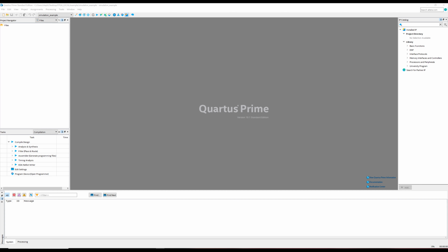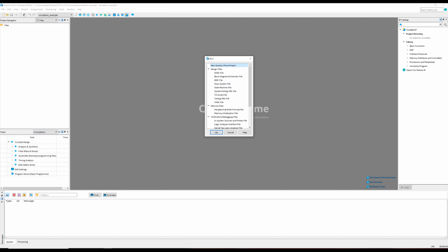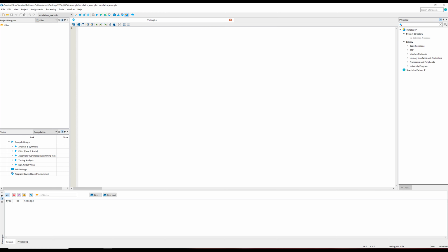Okay, in this video I will show how you can write a test bench and simulate any Verilog module or any Verilog design using that test bench using the Quartus design environment and Modelsim. So the first thing I need to do is go to File, New, Verilog HDL file, and I'll just paste my Verilog module code into this .v file.